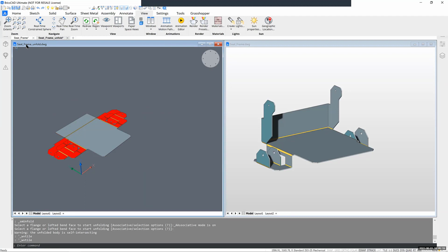And if you need the Start tab again, you can always type go to Start, I believe. Normally minimizing also works. So we now tiled them next to each other. And what we now want to do is edit the 3D part and see the unfolding change. So you need to click in the view or in the tab to activate it, and then you see it by the look from that appears. Similarly, you can click in the unfolded view, and they will be associated with each other.